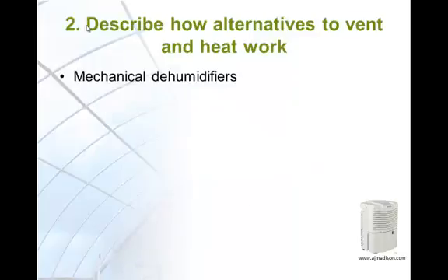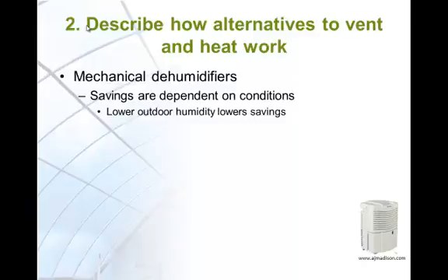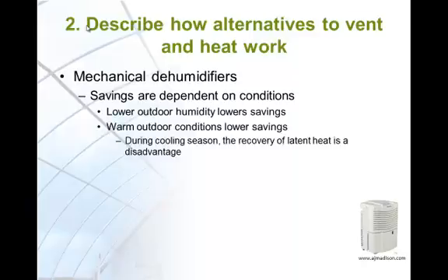As with a heat exchanger, the advantage of the mechanical dehumidifier is dependent on the conditions surrounding the greenhouse. As outdoor humidity lowers, the mechanical dehumidifier loses its advantage, and may lose its advantage completely in a warm environment where excess heat from condensation of water vapor is unwanted.